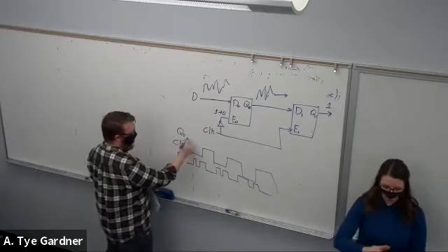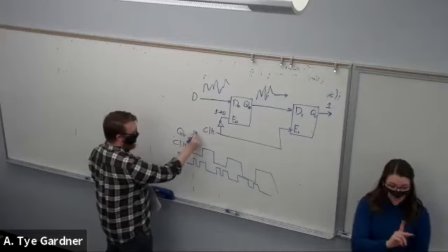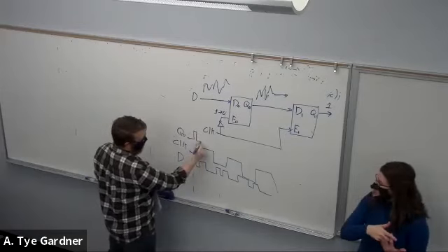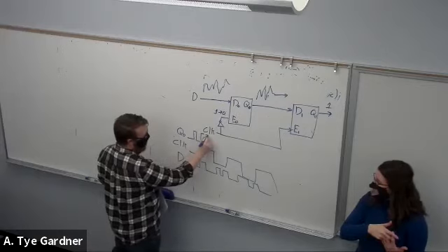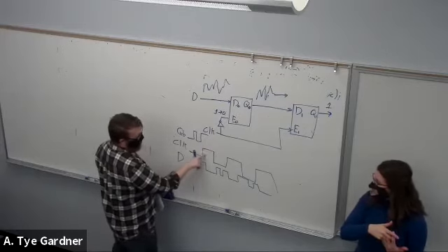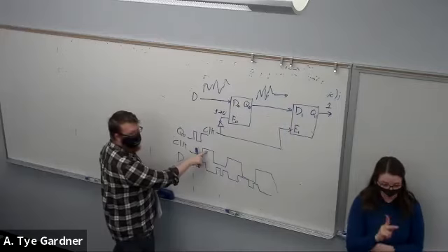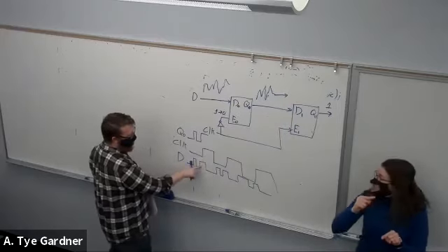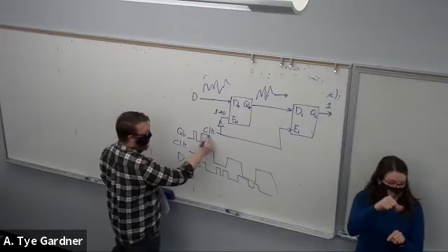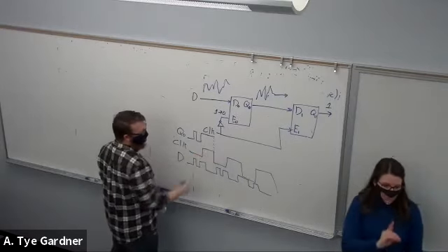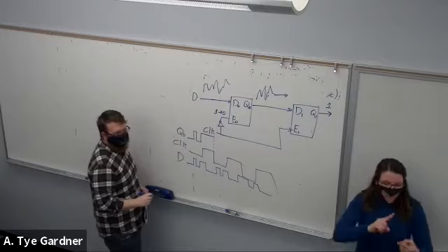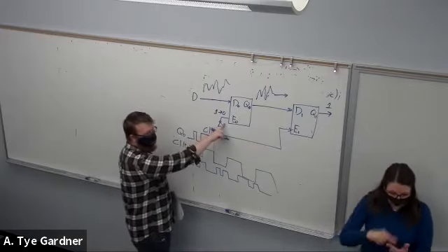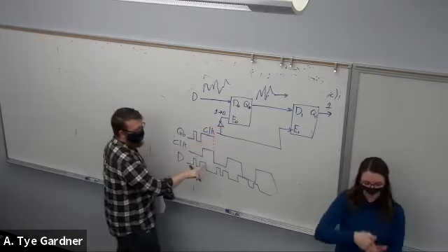So clock starts low, it's just going to follow up to this point where we rise. Now here clock is high, so we're no longer following D. We get to ignore it until this point where it drops back low. Because clock is inverted, that's why we're doing lows.